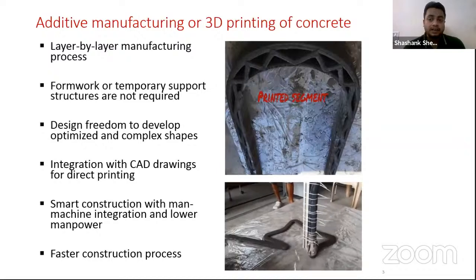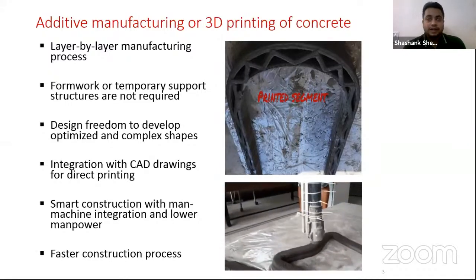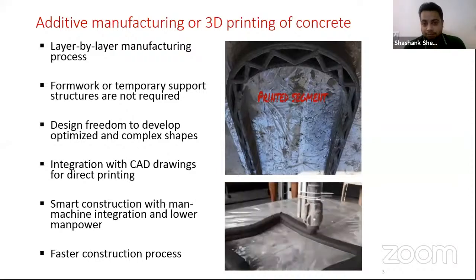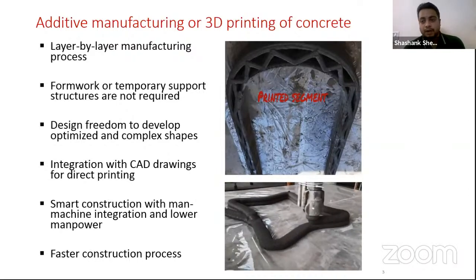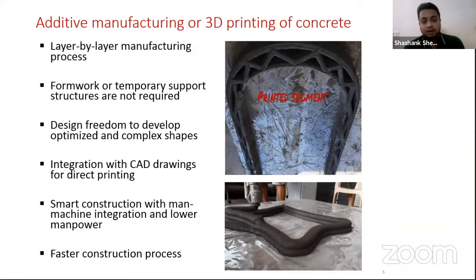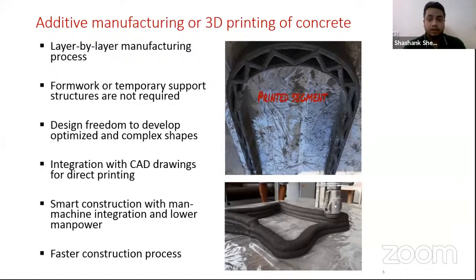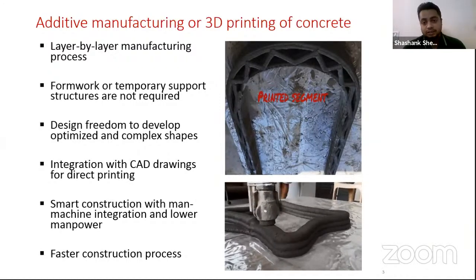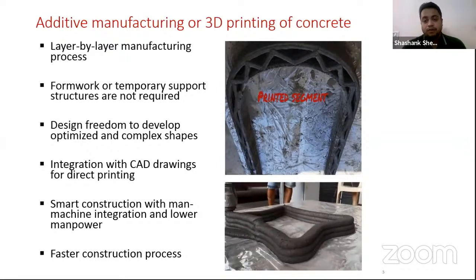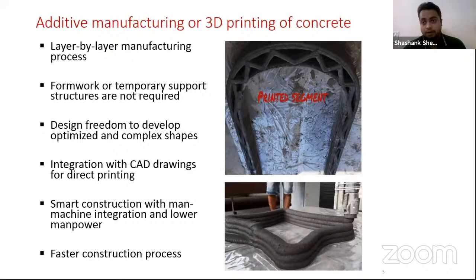We are talking about printing 3 meters in an hour. It's not like we are going to print 30 grams per hour like in usual plastic or metal printing. Here we are talking about 3 tons of material per hour. That is the scale of 3D concrete printing for construction, because even this 3 tons per hour is actually small for regular construction. In regular construction, we want 15 to 20 tons per hour output.